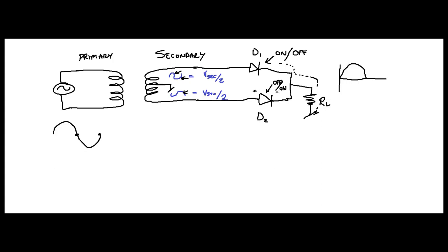It's just going to go right through. You're going to have one diode drop here, right? Across there, and it goes through your load resistor. So you're going to have the exact same signal, aren't you? Again, this is going to be one diode drop less than your VP secondary over 2, all right?